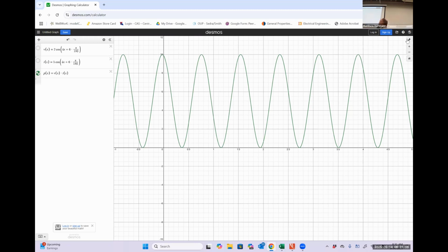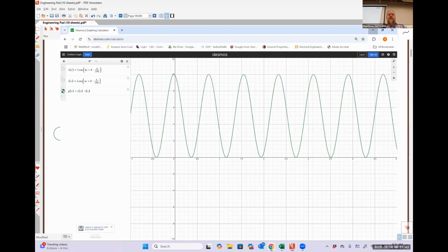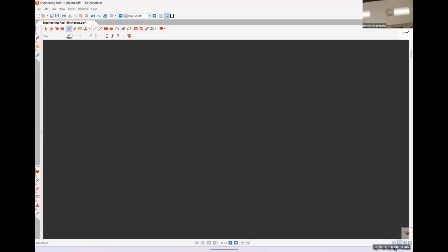Another thing we should be able to infer from this, and we kind of see it in the mathematical relationships as well: whatever the peak value of our instantaneous power is, exactly half of that is our average power, right? Because we're sinusoidally oscillating between 0 and that peak value. So on average, the value of this expression is just half of the peak. All right. So now let's look at our inductor relationships.